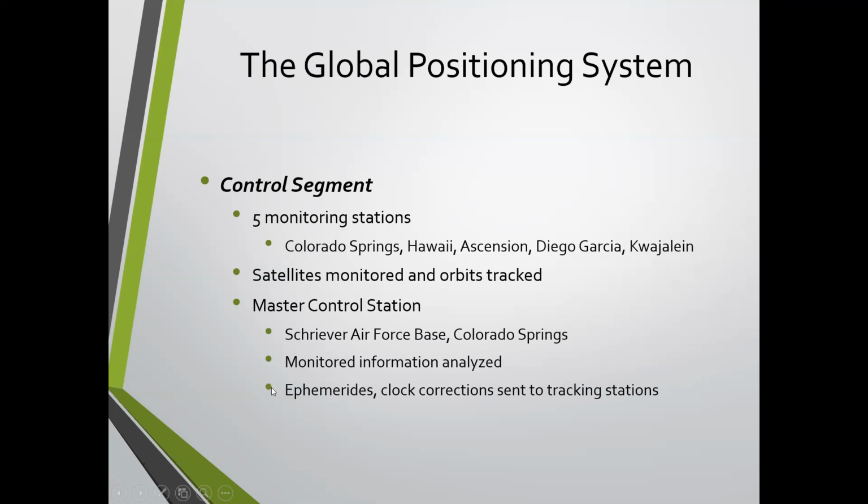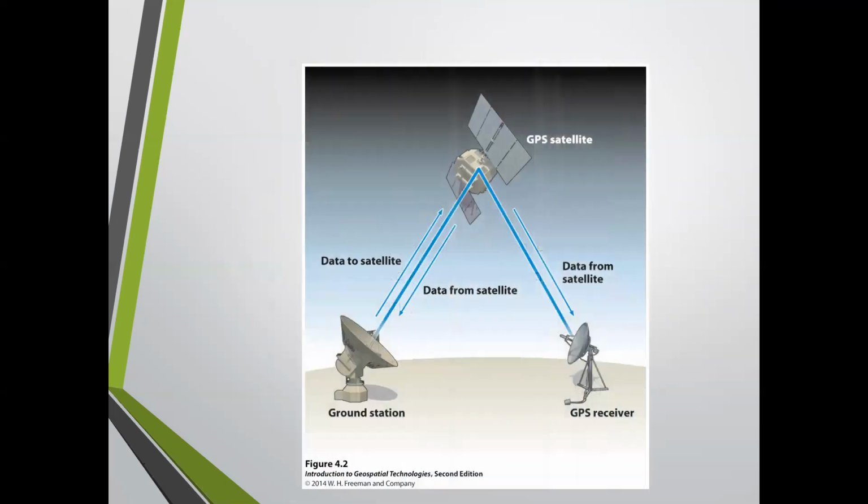And the ephemeris is developed every week, and it's uploaded into the satellites for the following week. I think they do it every Sunday evening, so they have a time frame that they do it. So you get the ephemeris there. It's good for a week, but it's basically from data that was a week before. So again, it's just kind of a best guess.